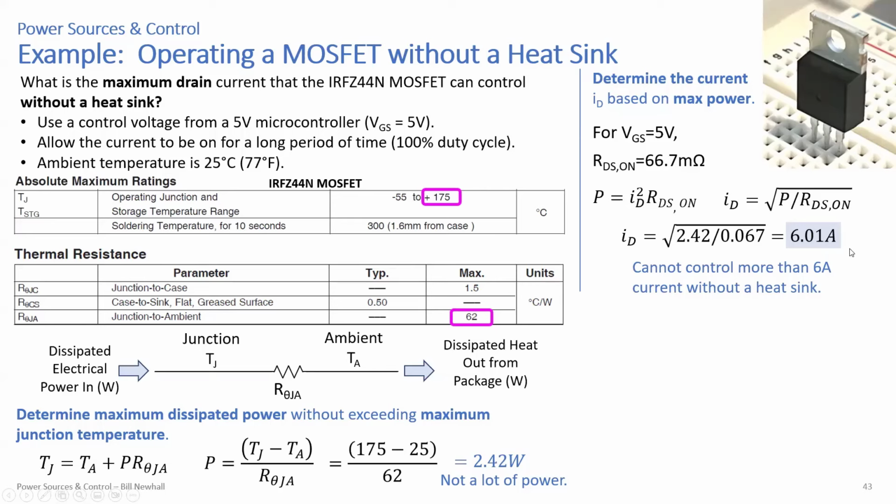And 6 amps, that's a reasonable current, right? The MOSFET's going to be really hot. I wouldn't touch it. If putting 5.5 amps for a long time, that MOSFET's going to get hot. But we know from the characteristic curves that we talked about that these MOSFETs can handle tens of amps, right? Well, when you get the heat out.